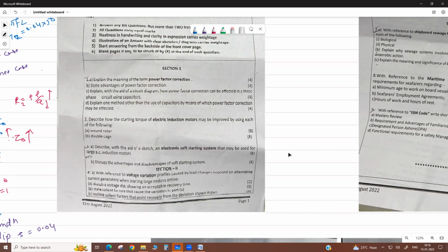Now if we talk about the star delta starter, by changing the connection configuration, the voltage is reduced by √3 times. During starting, it connects the motor in star, then it converts into delta. Okay, so here it reduces the current, but there is a transition period and a double cable is also required, double run in star delta.